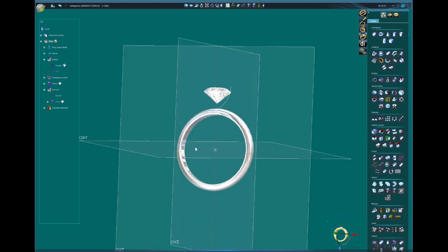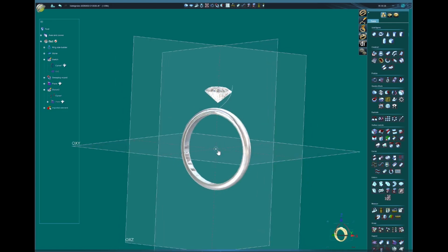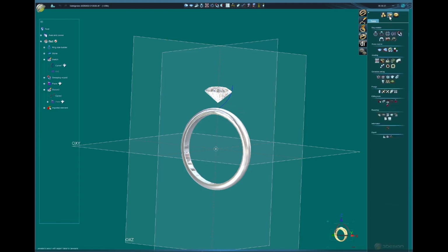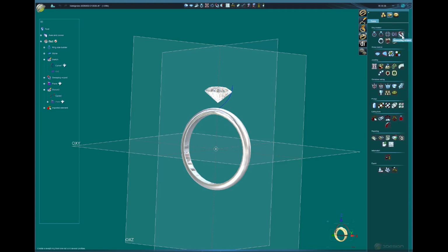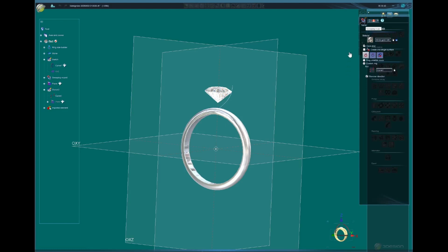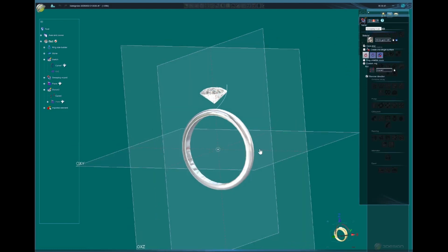So now we have the round shape here. You're gonna click the curve, go again to the sweeping wizard, click on it, and we're gonna have it again. So remember when I told you I don't like to use it on the shank?